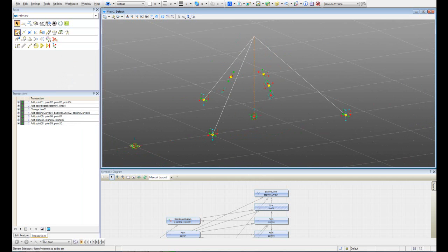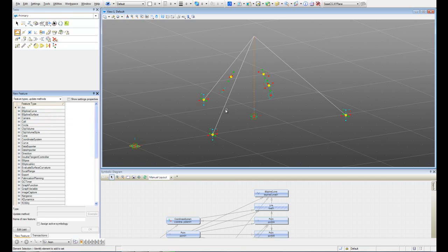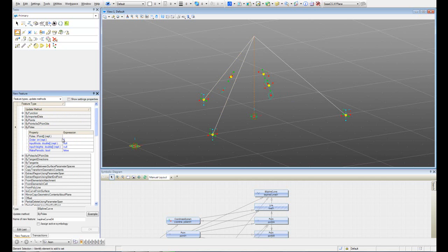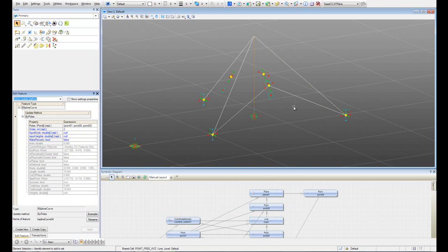And now the next thing that I'm gonna do is I'm going to create the same curves that I did, but using this point. So let's go to B-spline curve by poles, and I'm gonna do it using point of 1, 0.8, and 0.02. The order is going to be 2 because I want to make it a straight line. Order 2, that's what it means, and order 3, it's a curve. So let's hit OK, and we have that curve.